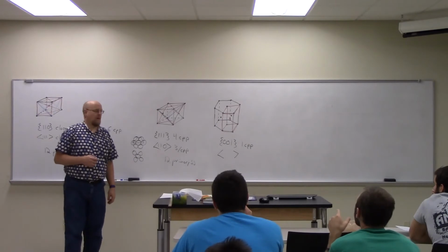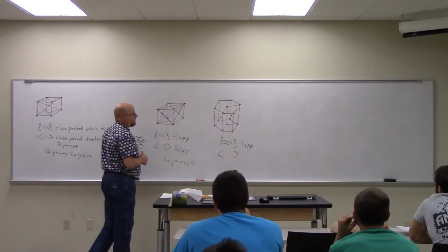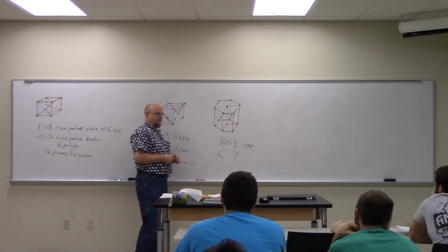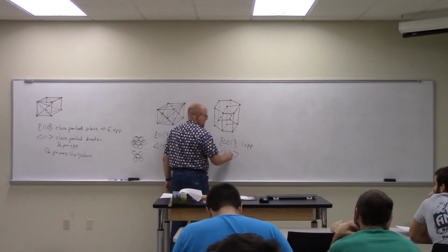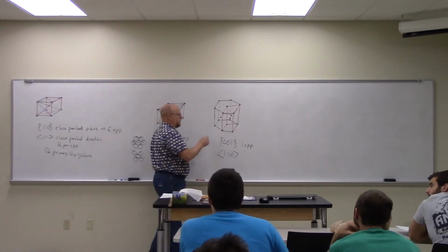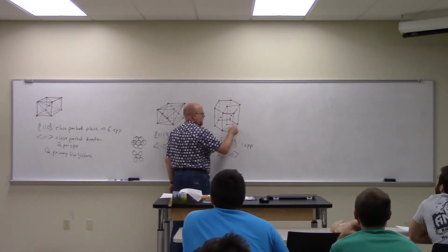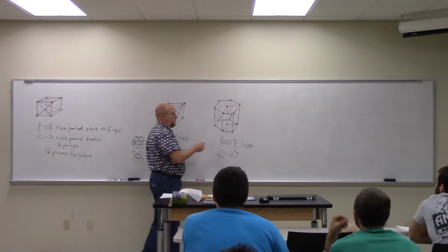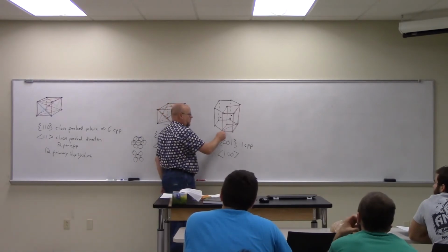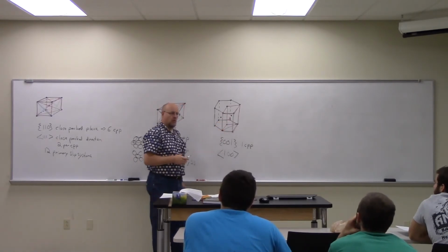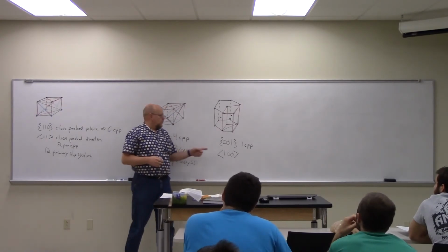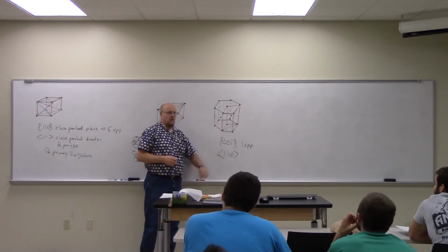110. Well, it turns out, actually, no. 1, 0, 0. 100. Because in reality, these are actually defined from this point. So 110 would be that direction. If they were defined from here, then 110 would be that, that's what I thought. But when you use the lattice, you start from the sharp corner. That's the definition of the origin. So 100 is this one, or that.